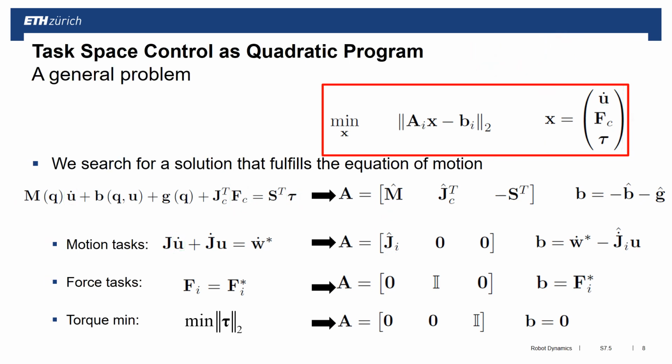Now what you see here is the most generic description of an inverse dynamics based controller for complex floating based systems like a quadrupedal system or a humanoid system, and we're going to see in the next lecture how we apply exactly this technology to quadrupedal robots.